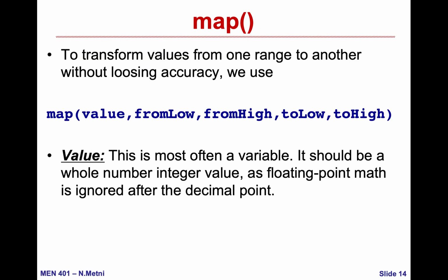What do I mean by mapping? Here, for example, if I have a value that is scaled between 0 and 1023 and I want to put this value between 0 and 256, I will use the map function where I put the value.